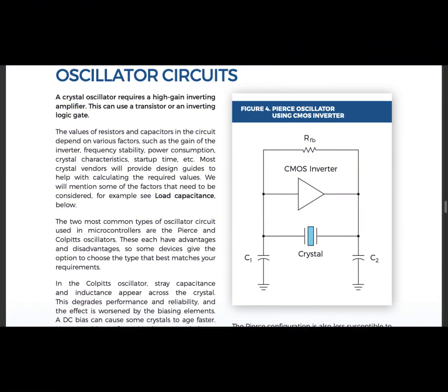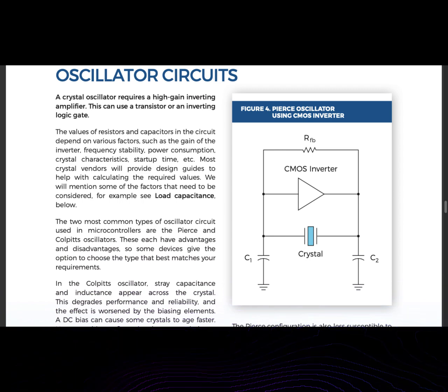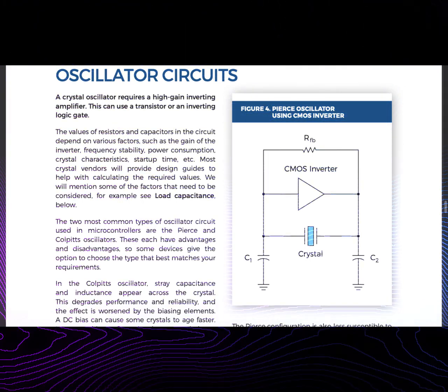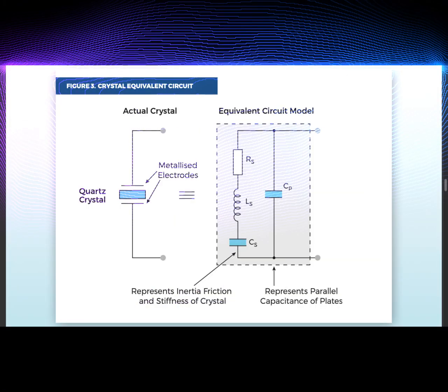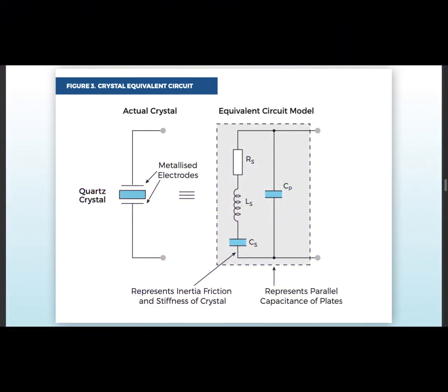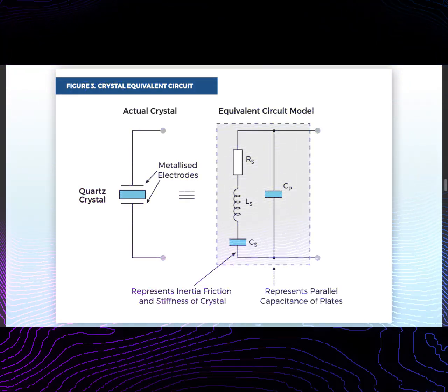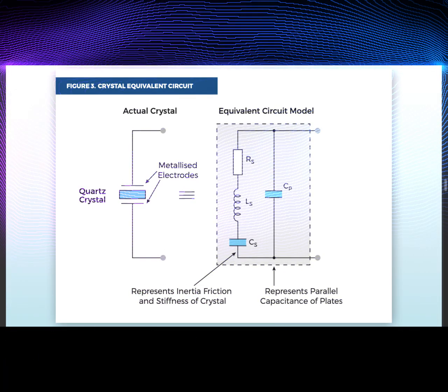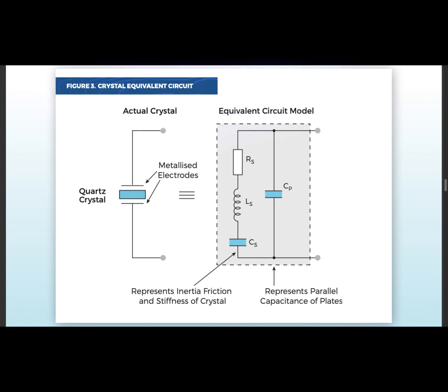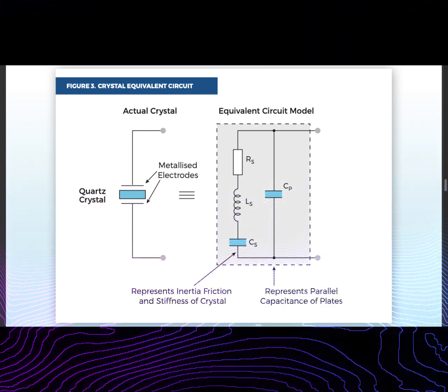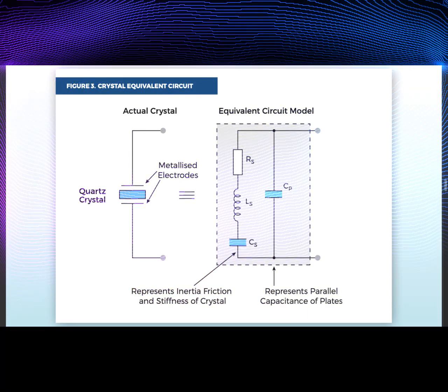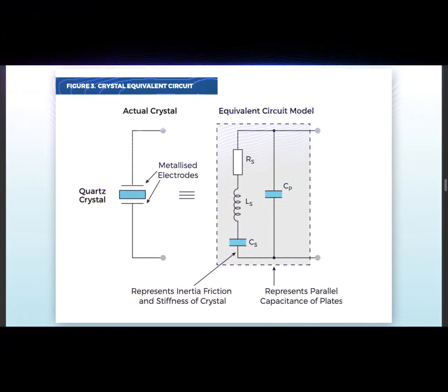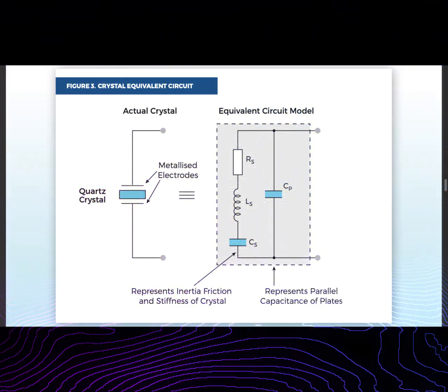So-called alpha crystals produced by this method can have masses of up to some kilos and are grown in about 20 to 40 days. During this growth process, the temperature should not exceed 573 degrees Celsius, to prevent a phase transition to a different lattice structure that will result in a loss of piezoelectric properties.